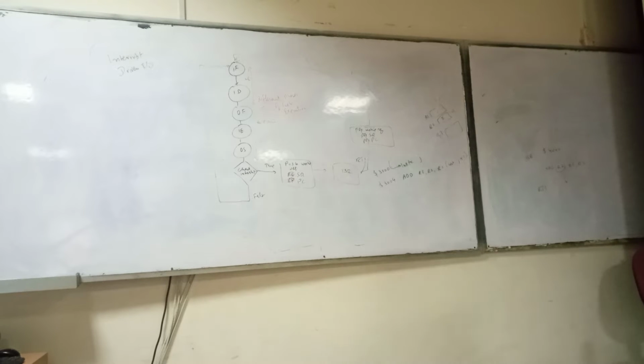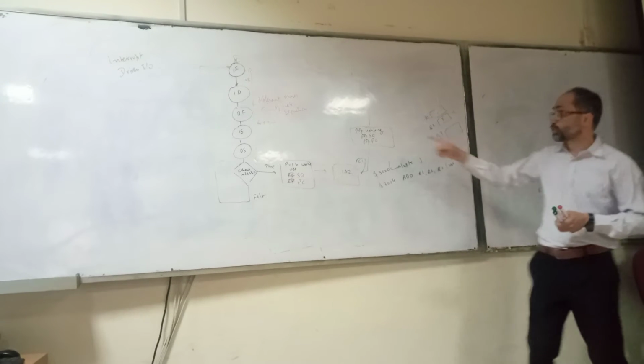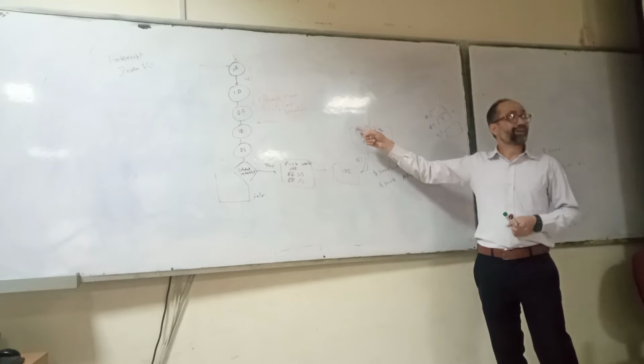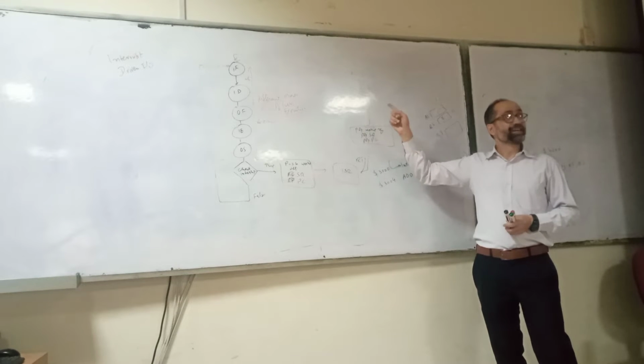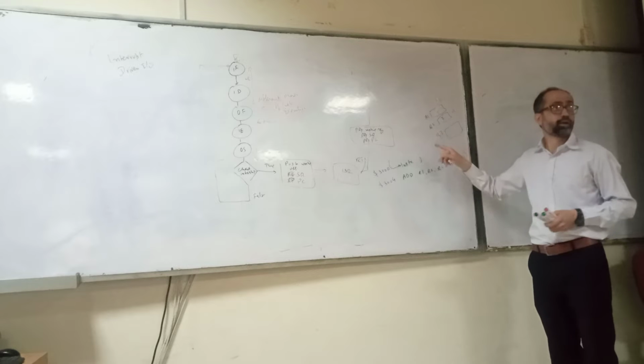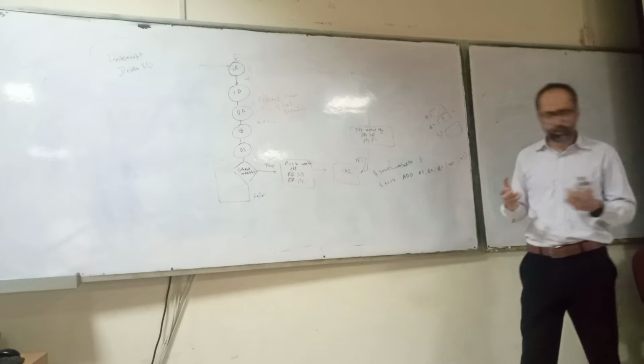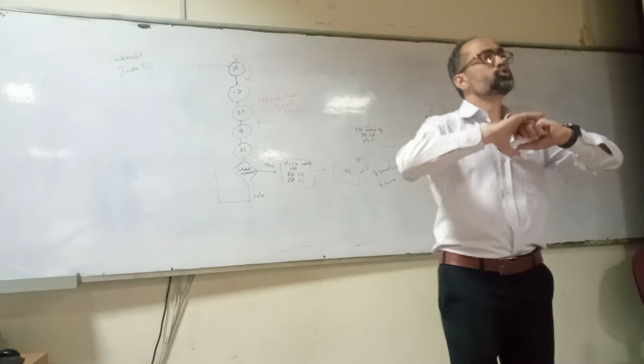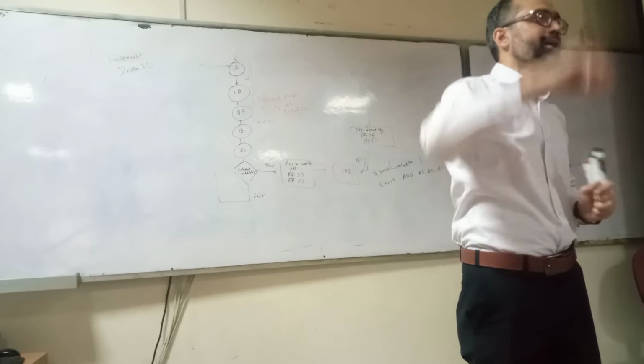So before jumping to the ISR, there are 2 methods. We also store the working registers on the stack. Which working registers is the program using? It is using R1, R2 and R3. And typically in some programs, they store all the working registers onto the stack.